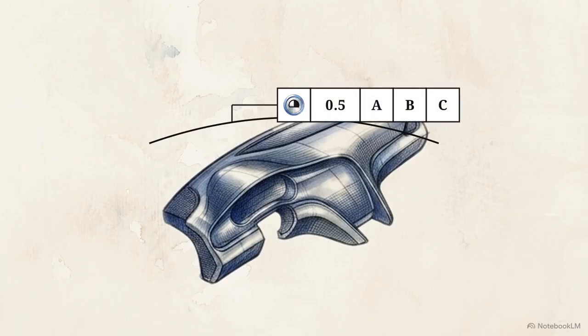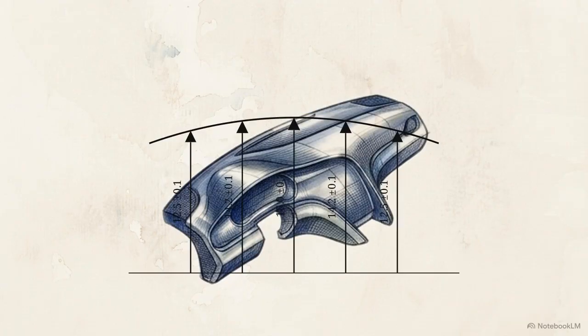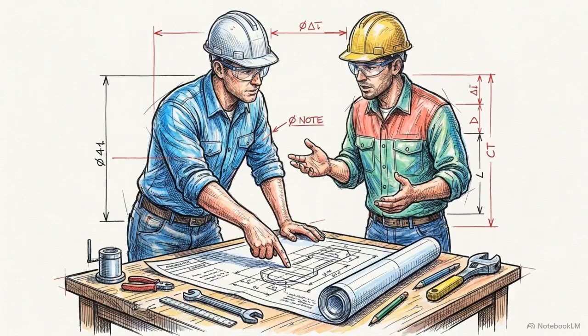Another frequent error is over-constraining the part. If a curved feature only needs to have the correct basic shape to function properly, adding datums to the feature control frame will force the manufacturer to hold tight locational tolerances that aren't actually necessary. Finally, designers sometimes rely on general linear dimensions to locate curved features without defining the exact shape and size of the tolerance zone. This creates ambiguity on the manufacturing floor and disagreements during inspection.